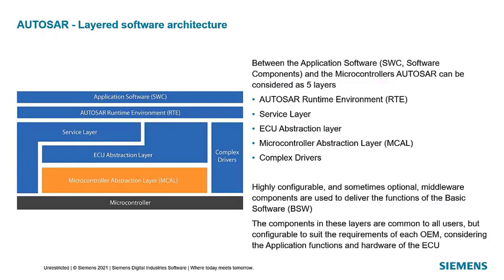Before we move to the Capital vStar solution, I would like to give an overview of one of the AutoSAR concepts, layered software architecture. As you might know, AutoSAR is the dominant standard for automotive software. All the major OEMs and most Tier 1 suppliers are involved. It includes a development process, abstraction from hardware and application, and the complete software middleware.